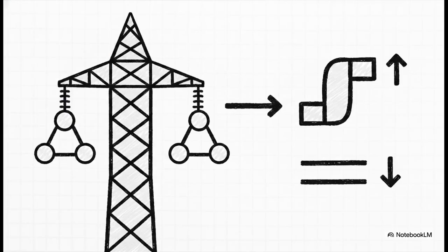This geometry sets up a massive, direct design trade-off that tower engineers wrestle with constantly. The inductance per unit length scales with the natural log of the GMD divided by the GMR. In practical terms, you need to space your phases further apart on the tower so they don't swing into each other during high winds. But that wider spacing, that higher GMD, comes with a severe electrical penalty. It directly raises the line's series inductance and lowers its shunt capacitance, completely shifting the line's natural electrical limits.